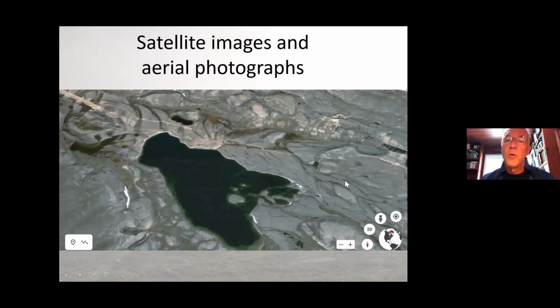Somebody that has a good eye, a geological eye, can see that there's a moraine here, a frontal moraine, and these are outwash deposits here. So moraine, of course, is a well-graded material. It's granular typically, but can contain a lot of silt, can be ice rich, can be frost susceptible, and also there's a risk of finding buried ice under moraine. So it's already information that's very useful for a project.